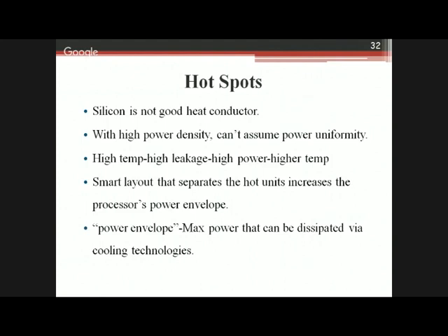What is the meaning of processor power envelope? The power envelope is the maximum power that can be dissipated via cooling technologies. Obviously you have to dissipate all the power so that the temperature is less, so that the leakage is less, so that I can avoid the problem of hot spots. That maximum power needs to be dissipated by the cooling technologies. So I have to increase this power envelope by putting the hot units separate from each other, and that comes under the designing part, and that is the meaning of smart layout.